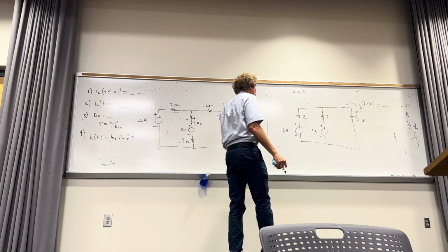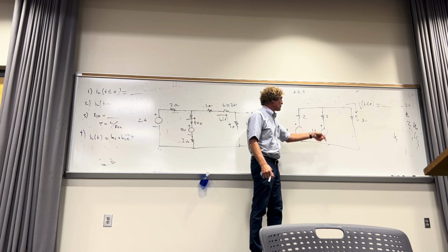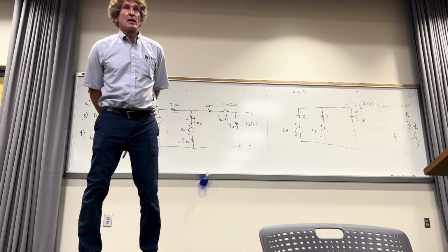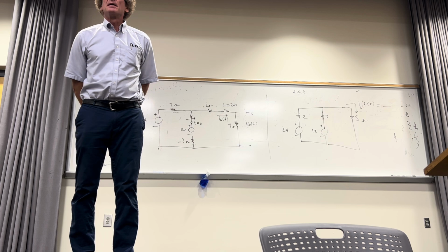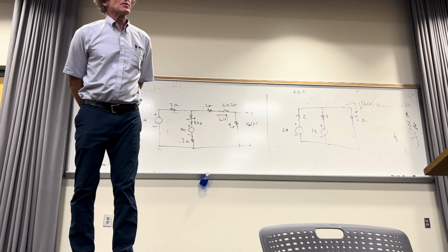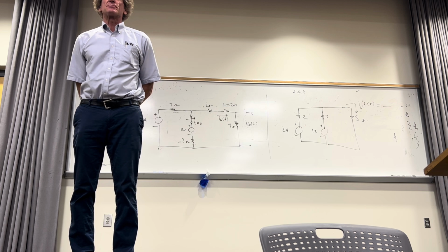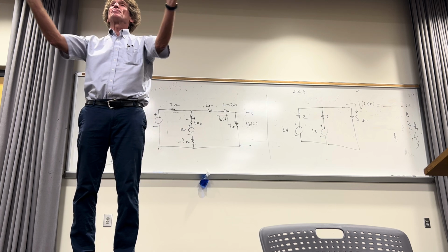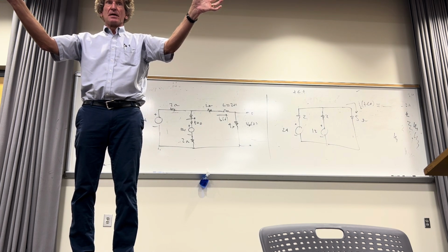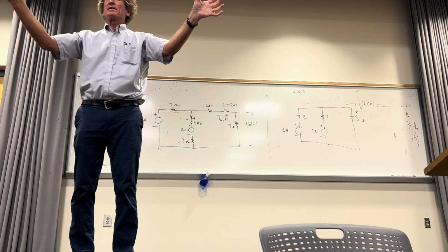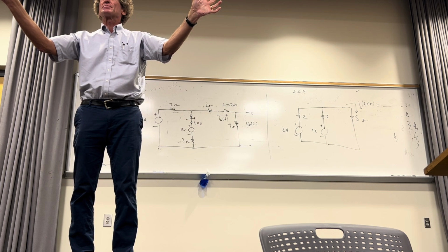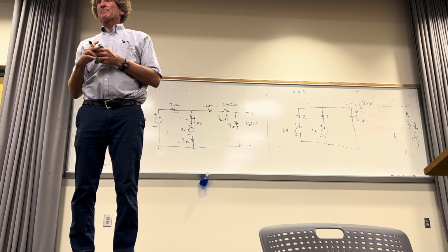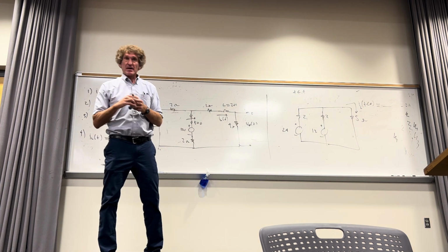Well, you can do it a lot of ways. You also could do 2 loops. How many see that? Yes, sir. How can you combine the resistors if there's a short circuit in between? Class, anybody want to answer that? Will it matter, if you just want the current, for 2 series resistances, what order they're in? What's always between the 2 resistors? Wire. Correct, class? It doesn't matter if you put one in front of the other. The combination is the same. That short circuit has nothing at all to do with the resistance values. It's a wire. I hope I answered your question. Sometimes students can answer it better than professors. I found that out. Grad students are the best.